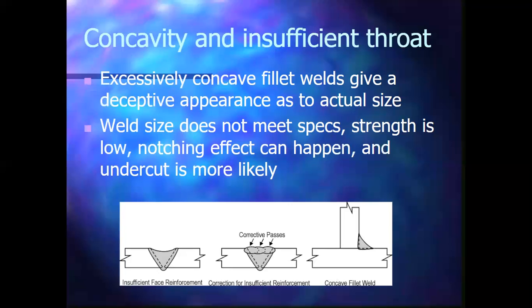So the way they actually measure these welds, guys, is if you're given a spec, it says they want a 10 mil or an 8 mil effective throat. An effective throat is drawn from the very deep throat of the weld right through the center of the face. That's going to be our face. But the way we measure welds is we draw the biggest right angle triangle we can within this weld section. So it would basically be from here to here, because you could draw that straight line there to there.